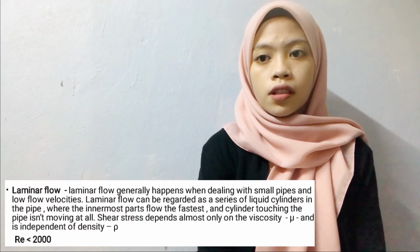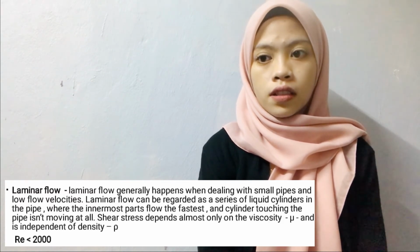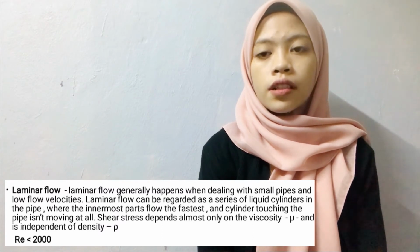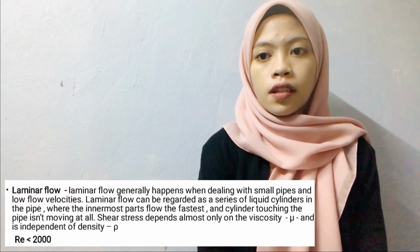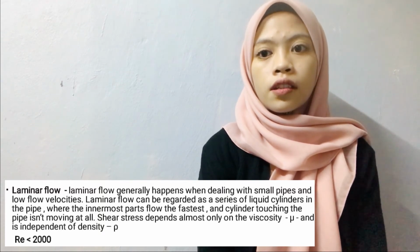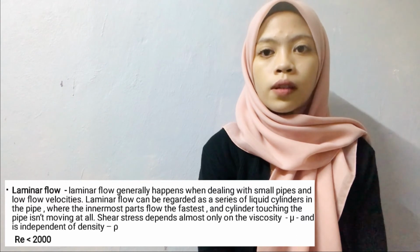Laminar flow generally happens when dealing with small pipes and low flow velocities. Laminar flow can be regarded as a series of liquid cylinders in the pipe, where the innermost parts flow the fastest and the cylinder touching the pipe isn't moving at all. Shear stress depends almost only on the viscosity, that is dynamic viscosity, and is independent of density, that is rho. Reynolds number for laminar flow is below 2000.